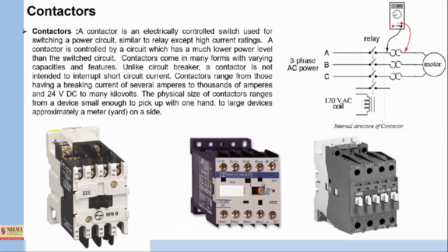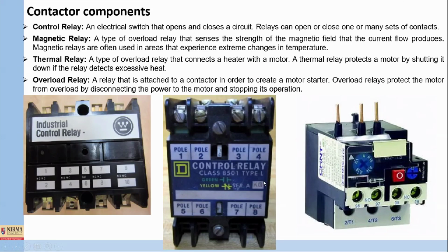Further, we'll also see the demonstration of contactors, how contactors have been connected, particularly in the motor case, at the end of this particular experiment. We'll see the demonstration of different kinds of contactors, particularly when we switch on the motor by using a starter. We'll have either forward-backward starter, star-delta starter, or direct online starter. They will be done through these contactors. We'll check that again. Now let us move forward.